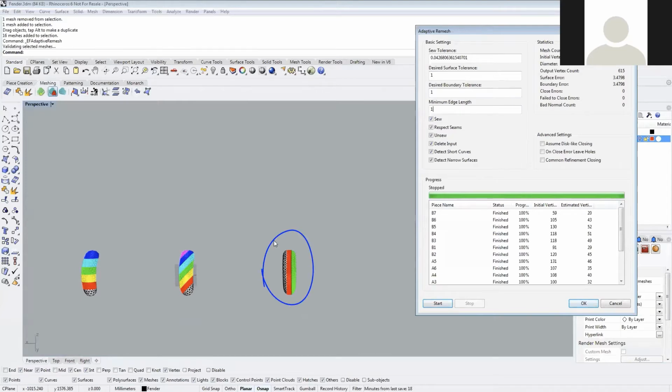So last time we only selected basically this piece here, computed the bounding box and gave us our desired tolerances. Because we've added physical separation, we've changed the size of the bounding box, but these values are still in model units. So when we look at this 1 unit surface tolerance, this is actually 1 millimeter. So we're allowing a maximum deviation of 1 millimeter from the original mesh to the new mesh.